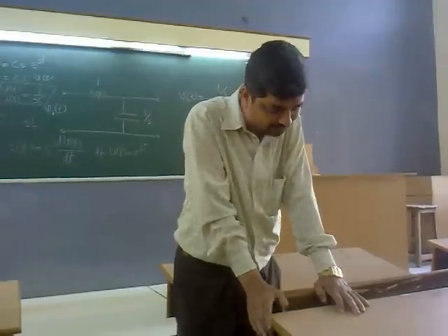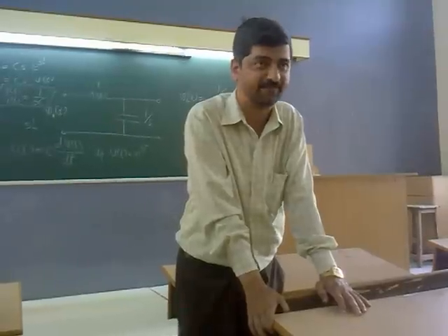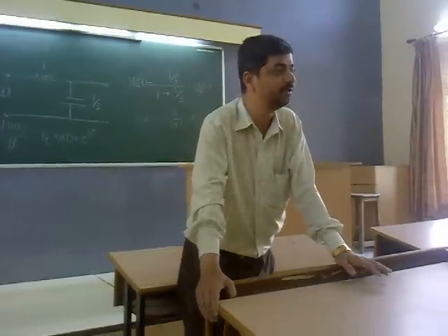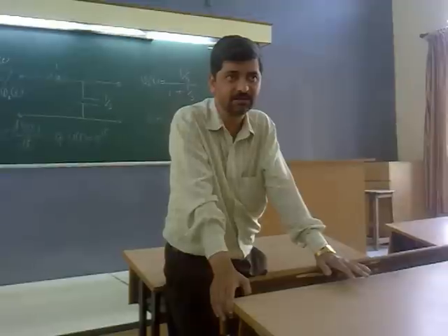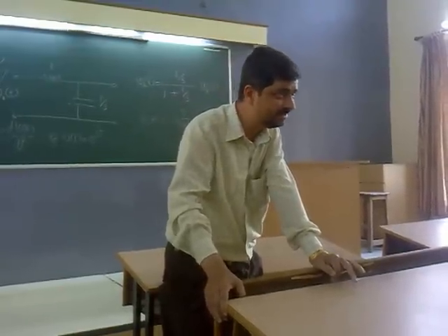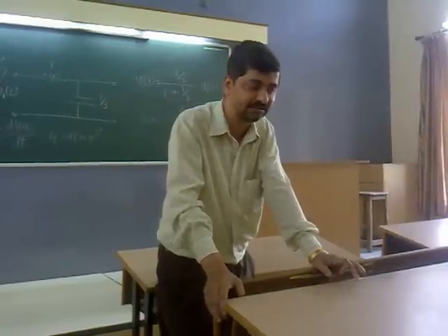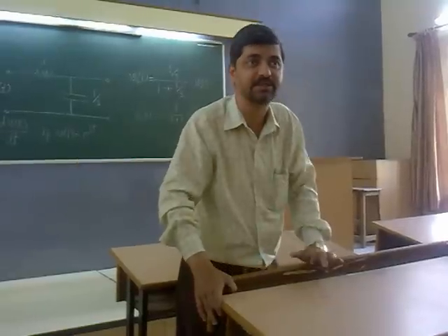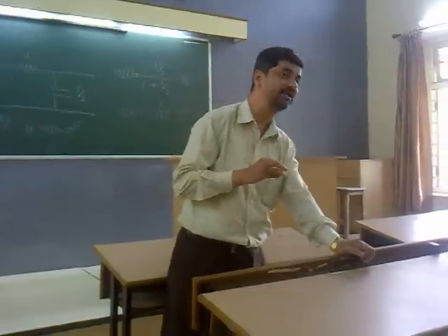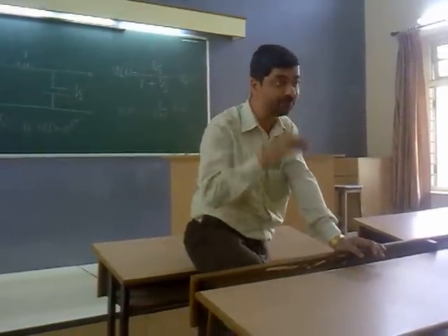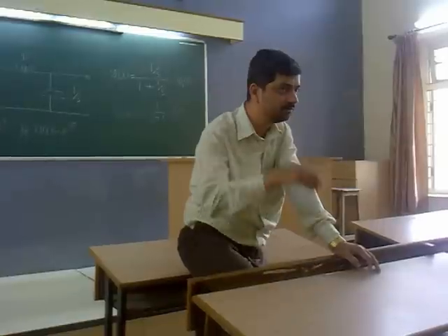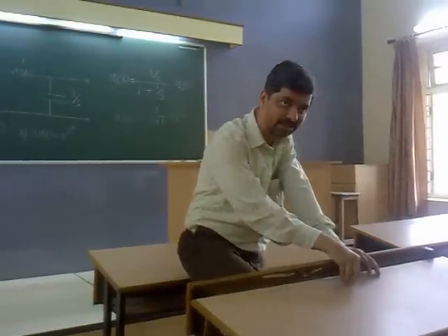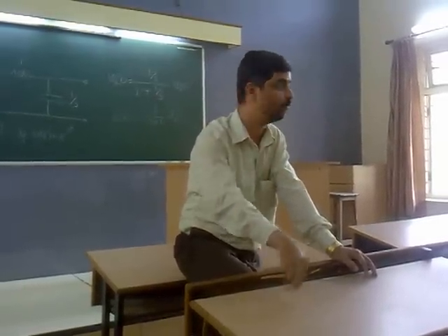we can take help of the superposition theorem. What does the superposition theorem state? If I apply two sources simultaneously, then the output would be the same as the summation of two independent outputs with one taken at a time. Now, what is the use of e raised to st? The use of e raised to st is that it converts the differential relationship into a scaling relationship. Therefore, we want to use that.